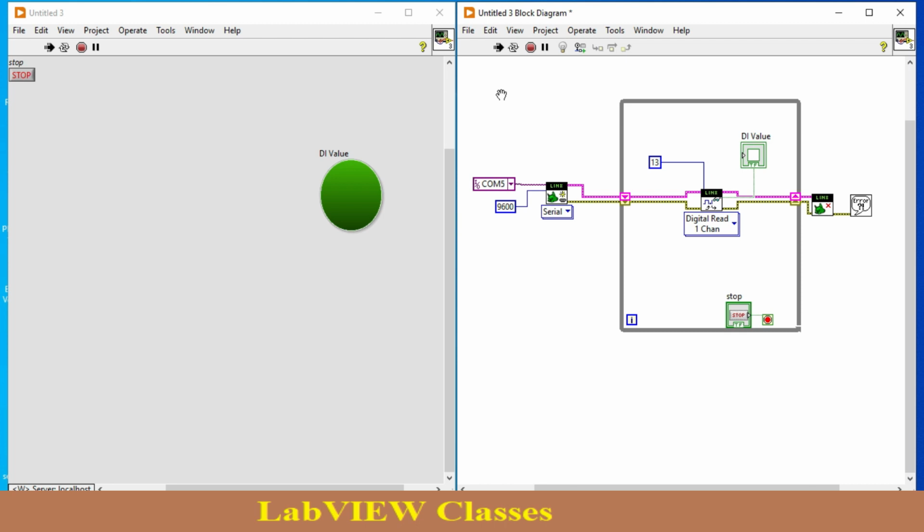On the hardware part, you are more aware than me because you deal with it daily. When you assign a port on hardware, you need to connect it to some value, maybe a positive value or VCC, or you make it ground, like you told me, pull up position or pull down position.